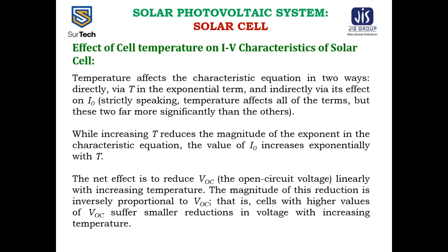For most crystalline silicon solar cells, the change in the open circuit voltage with temperature is about 0.50% per degree centigrade, though the rate for the highest efficiency crystalline silicon cell is around 0.35% per degree centigrade. By way of comparison, the rate for amorphous silicon solar cells is 0.20% to 0.30% per degree centigrade, depending on how the solar cell is made.